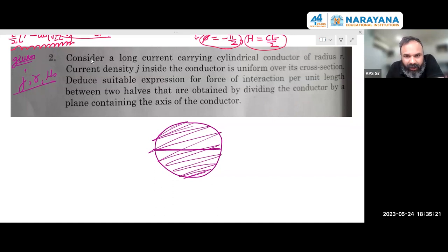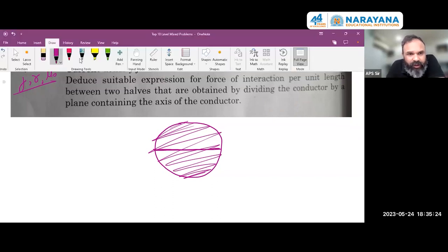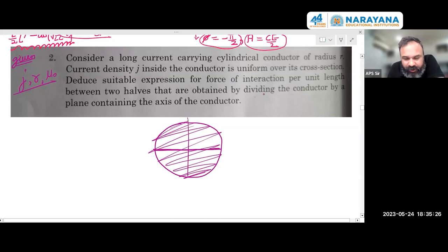Now, the idea to observe this problem is, I'm observing the lower half of this solid cylinder. I want to write the force on the lower half. So what I've done is I've taken a hollow half cylinder of radius small r. So maybe take a radius of x and cut a dx here and just cut this lower hollow half cylinder having thickness dx and radius of x. So go to a x and cut this element dx here. Then just try to write the force on this part.